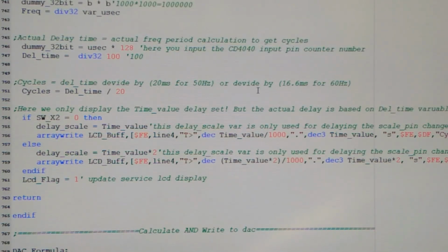And depending if it's times 2, instead of changing the calculation, I leave the calculation the same. So I'm still using the 1 to 8, that means Q8 of the CD4040. And when I'm timesing the value by 2 to read off the 256, I didn't redo the calculation for 256. No point.